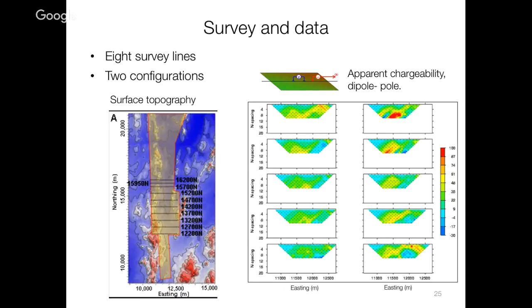The geology was running kind of north-south. They did 10 lines of data, and in the DC resistivity, we put a current here and then measured the potentials. Then we also did a current here and measured the potential. So we excited it from two ways, doing the same thing here. The pseudo sections look like this. And you can see there's definitely something there. So this is chargeability sections here.